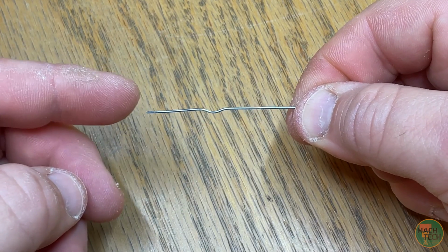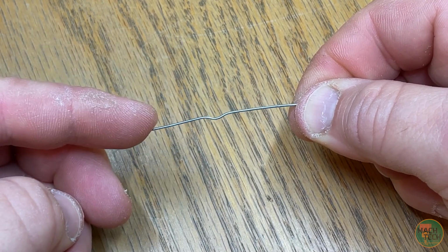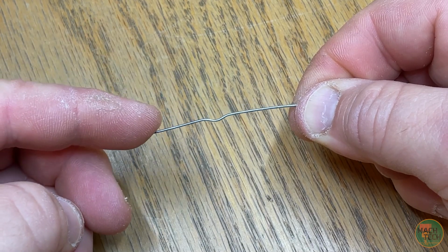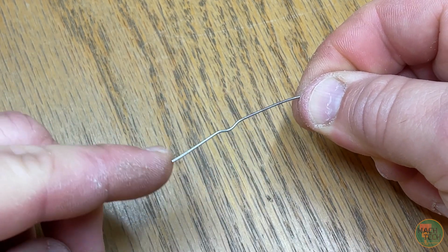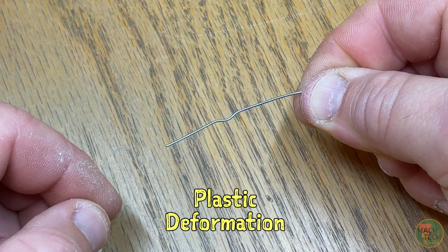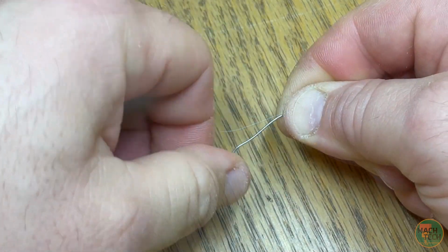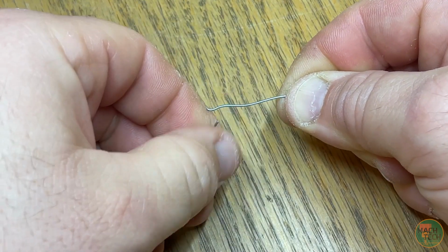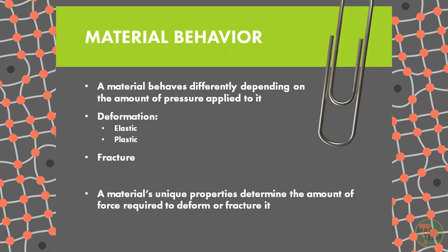For example, if I apply a small amount of pressure to this paper clip, it'll bend. But then it will spring back like a rubber band to its original shape when I remove the pressure. This is elastic deformation. If I apply a little more pressure, I can bend the paper clip and it will take on the new shape. This is plastic deformation. And if I apply even more pressure, I can get the paper clip to fracture completely. In this case, I actually have to bend it back and forth a few times to work harden it before it will fracture. This steel is pretty soft. The pressure at which a material goes through these three modes depends on the unique properties of that material.